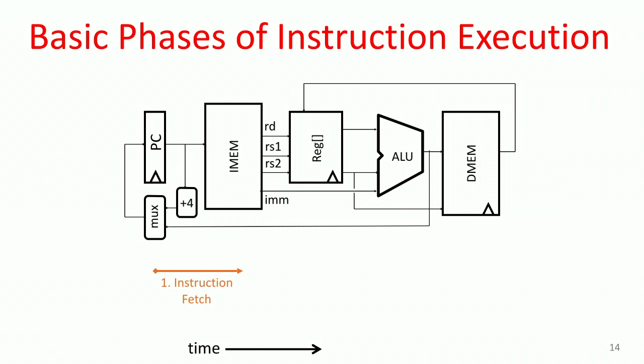And we'll split that instruction into these various fields that I showed you previously in the instruction encoding. That part is the decoding: we decode the instruction, pulling it apart, looking for the various fields. At the same time, kind of in parallel, certain fields of the instruction get sent to the register file to use as the addresses into the register file. And so we do register read. This propagates into the register file, and the register values then come out of the register file into the ALU.